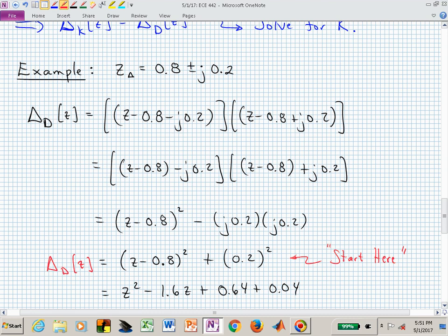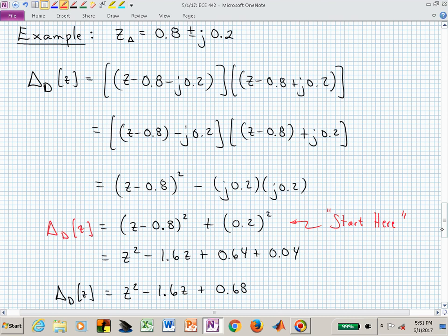But once you have this, now you have a second order polynomial that you can build. This is where we want to live inside the unit circle based on this characteristic polynomial, and this is what we use to force these closed loop, or full state feedback gain values, the K1 and K2 in this case, to match this polynomial with our characteristic polynomial that's a function of those adjustable parameters, K1 and K2.